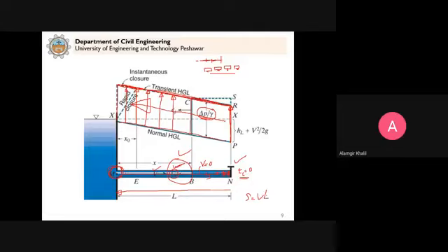Now S is your L, this L. And V is the velocity of the pressure wave, because this is the effect bringing, so that is equal to Cj. Why do we say Cj? Because we are now considering the pipe and the fluid both as elastic. And time is your T. Clear? So now from here, we can write down that T is equal to L divided by Cj.